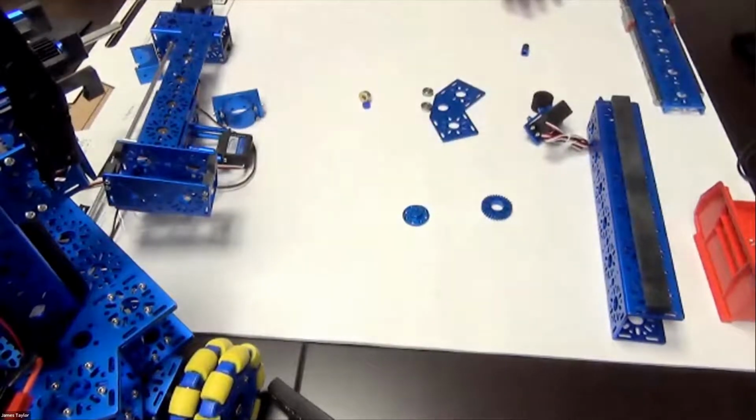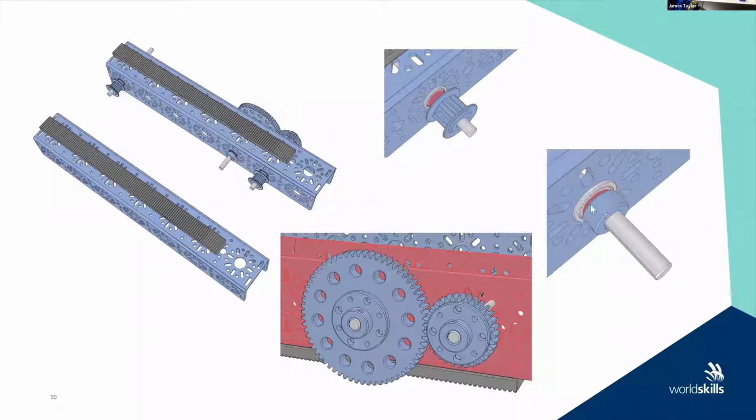So just a point on that elevator mechanism when you're going forward. There's, like I said, the spacers there with the pulley, a 1mm spacer here with the shaft collar in your design, and there's your flange bearing inside of your channel. And on this side, we are mounting the hubs to each of the gears.